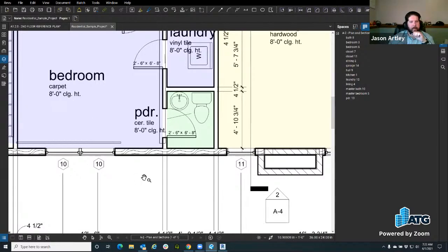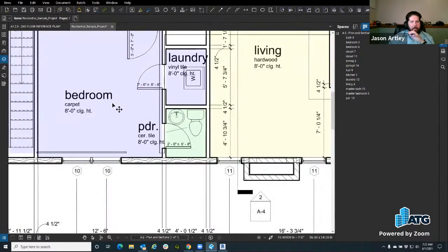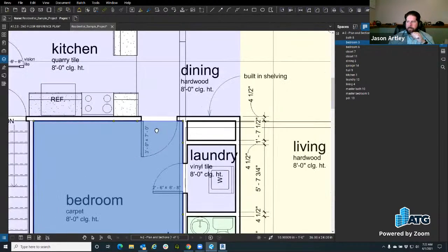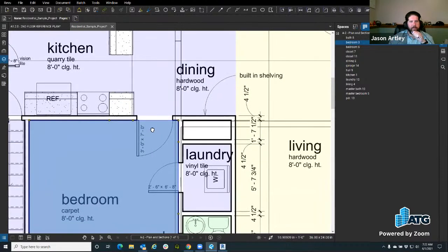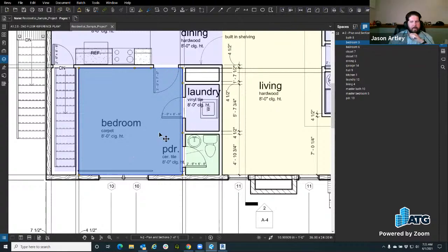Yeah. But if you went to go measure this, there's probably a substantial amount of square footage that's not accounted for, which could add a couple $100 to the project if you're just looking at flooring. Interesting. But that's because of how these rooms were made in Revit, right? Correct. Not accounting for the opening. But the difference should be taken up in any waste calculation. Ooh.